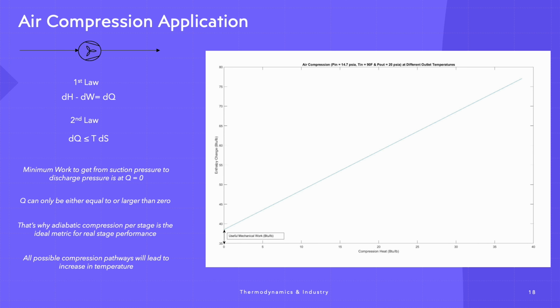So with that, we'll be going into our industrial examples, and we are going to be taking a pretty simple example in our system. As you can see, taking an air compressor as an example here, with the given conditions, we have suction conditions around atmospheric pressure, 90 F temperature, and we are looking into the discharge pressure to be around 20 psi.